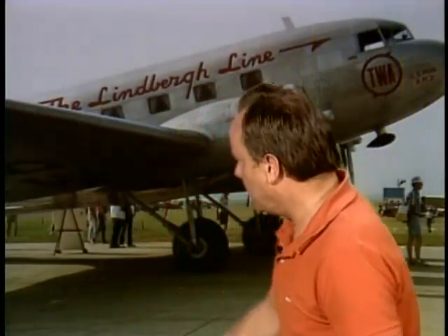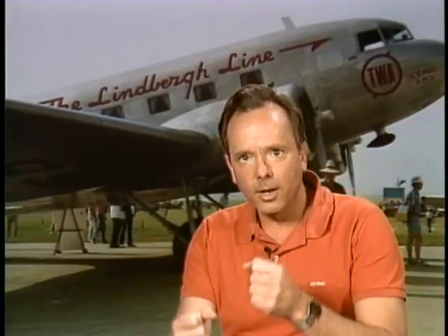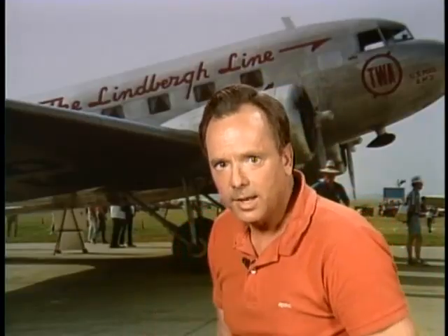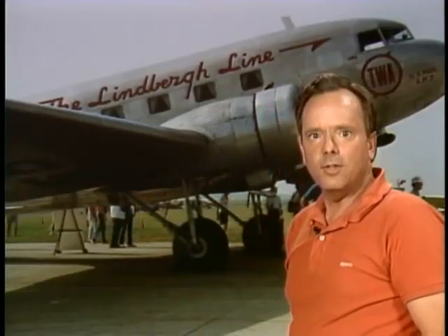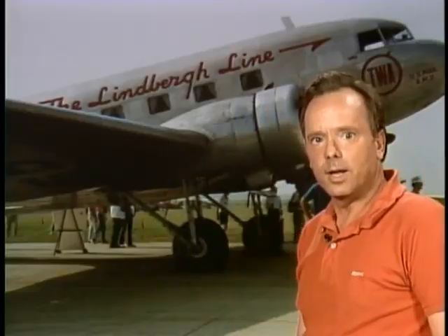Now let's talk about cable tension. Sometimes big aircraft like a DC-3 or a Constellation has a tension regulator in the flight control cable system. That's generally used in a large all-metal aircraft, and it's primarily to retain a set tension on the cable. So you might have a tension regulator in this airplane if you were flying a DC-3 or a Constellation.